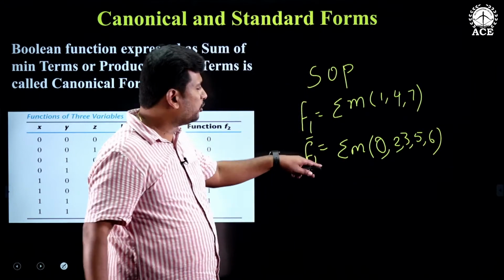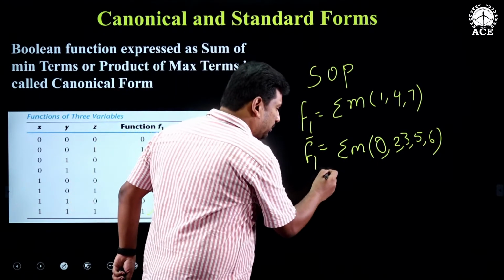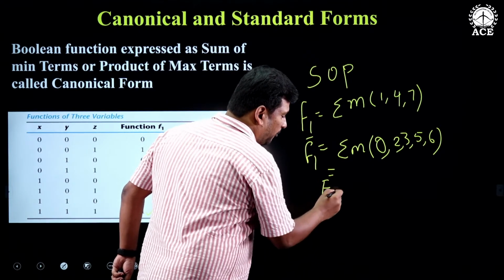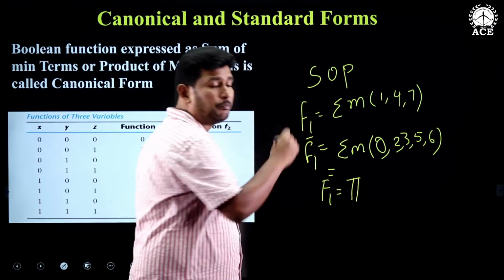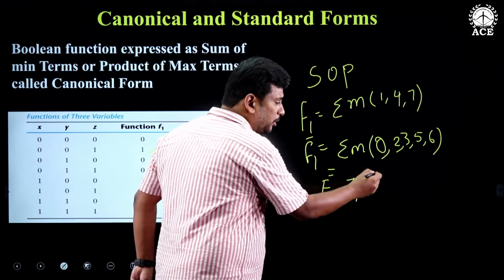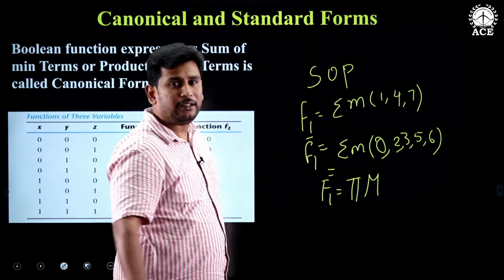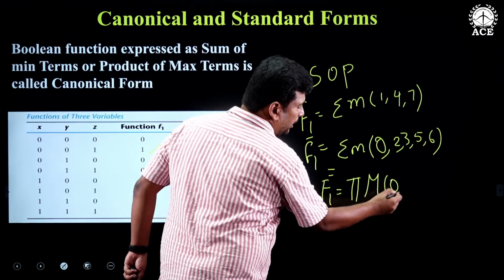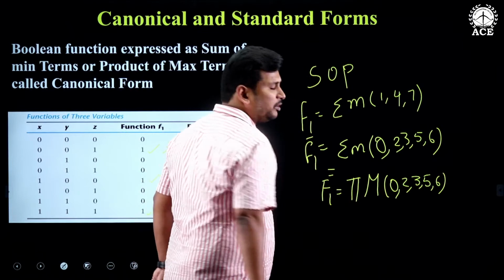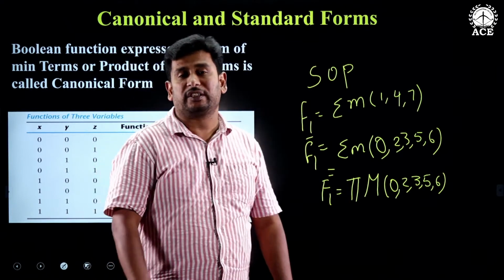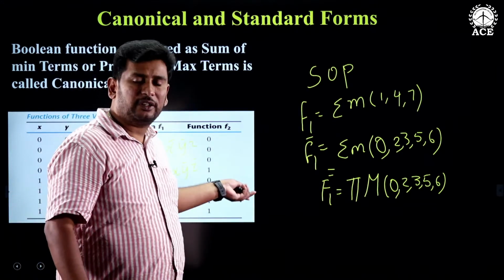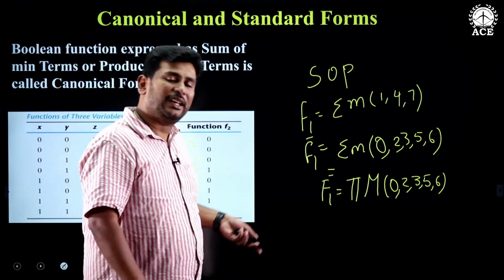So this is called the complement of a given function, and let me twist you by saying that this is the same as your f1 represented with product of sums, product indicated with pi and maximum terms indicated with capital M, and you can write this same as f1. So the minimum terms missing in your function will be part of the product of sums representation for that same function.